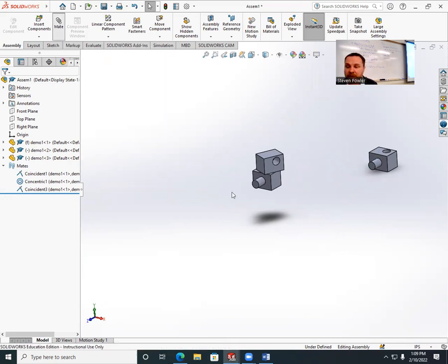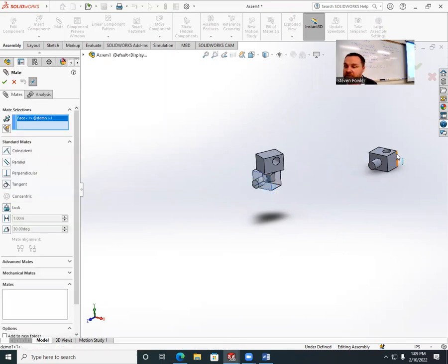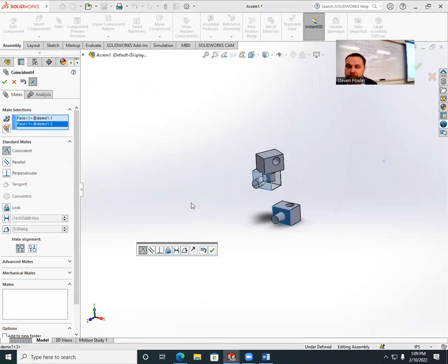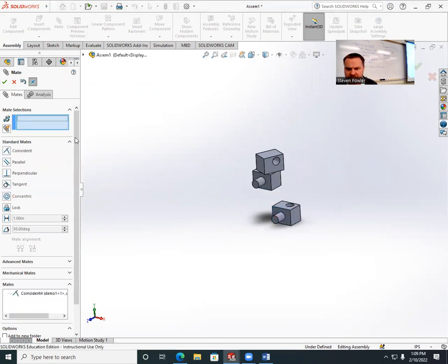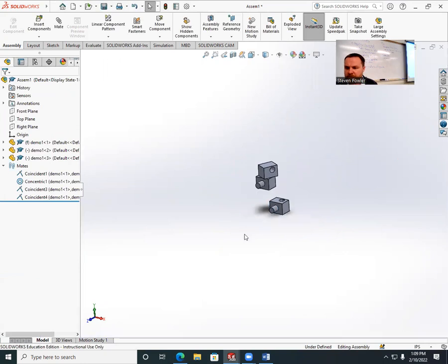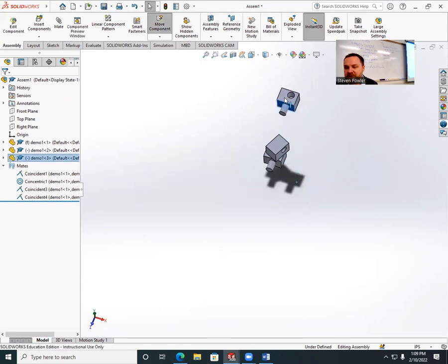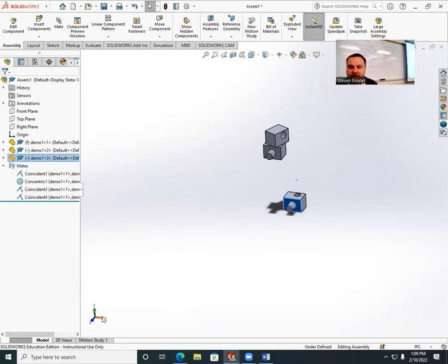So what I'm going to do is say, well, let's mate this face to this face. And it's still, Steve, they're still not. No, well, yeah, they are. They've actually done exactly what I told them to do. It can still just exist in a variety of ways. But see, here's the thing. Now I've defined in the X and the Z direction how these two interact, but I've not defined the Y direction. So it can still move in the Y direction.